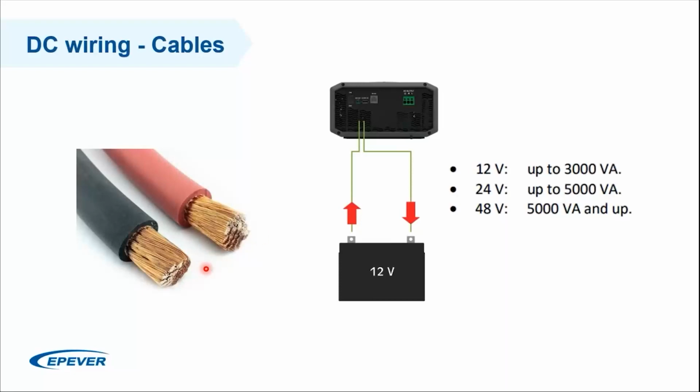In some inverters and some charge controllers, you might face 2 positive terminals and 2 negative terminals for the batteries. The reason is that the specific unit provides high current, and it's a high power unit that demands a higher cable thickness. So the trick applied here is to use 2 terminals as positive and 2 terminals as negative on that inverter charger, for example. With this trick, you can still use the same thickness, but you are doubling the cables that you are using in the system.